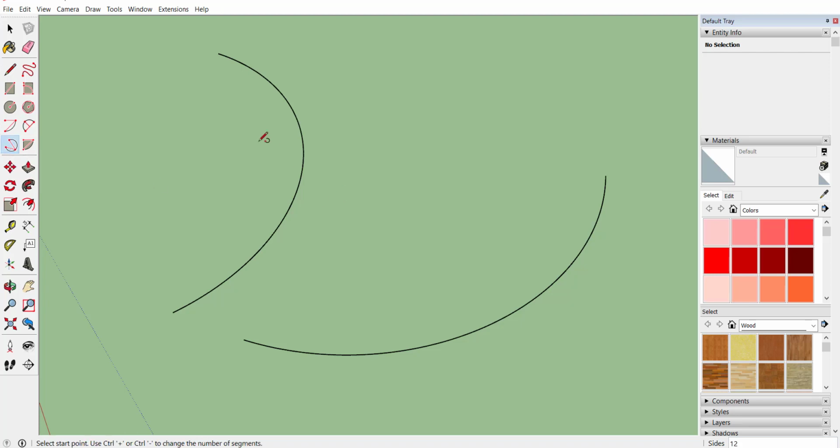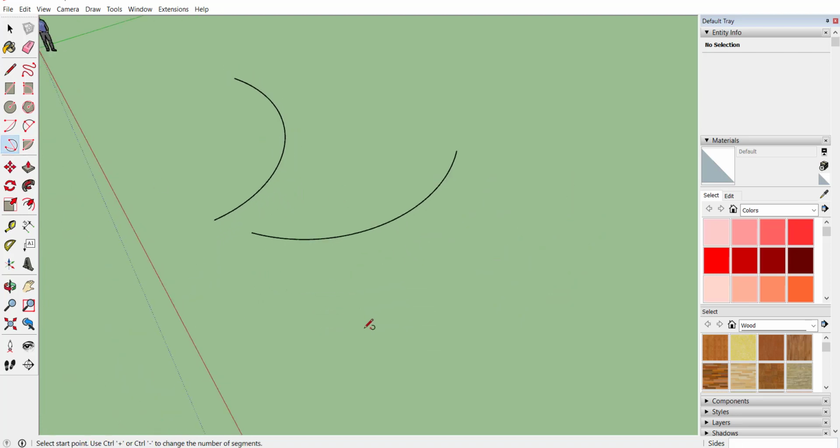Now 3-point arc will also work in a similar manner. Select the first point, second point and drag your mouse. Now the arc generated will pass through first and second point and you just need to decide the angle. Let's consider I want an angle to be 250, then just type 250 and here is your arc.